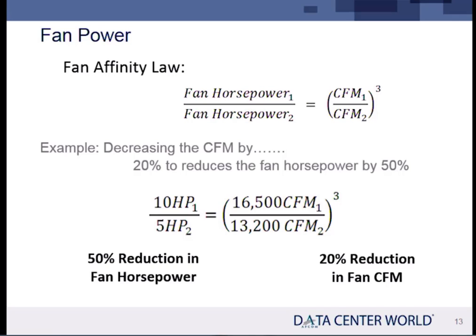That's a big number. And this is where variable speed fans or EC modulated fans have become very popular because you can now begin to move the fan number down. For many years, this was a constant. We were stuck with what we had, and it didn't work very well. Nowadays, the opportunity for EC fans or direct drive fans that can be modulated so that their speeds can go up and down based on a sensor can improve your situation greatly because it'll save you money in fans and also increase your return air temperatures.